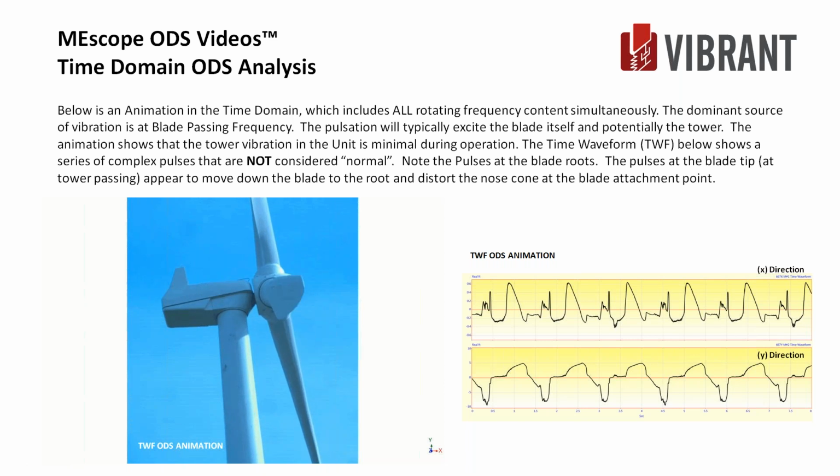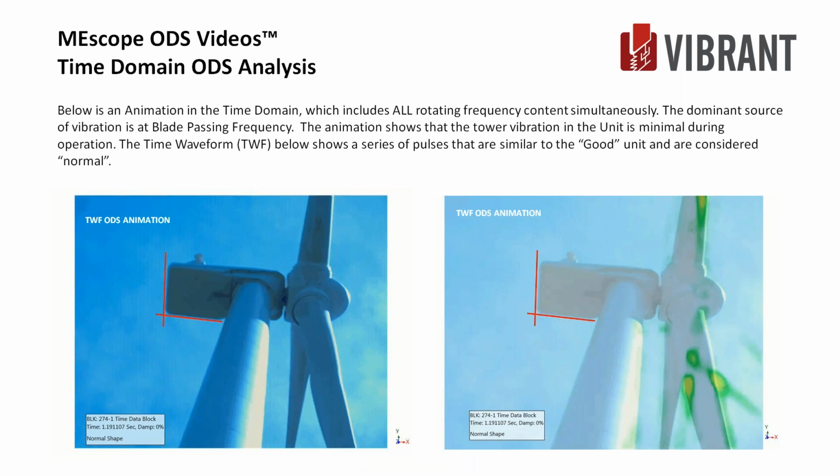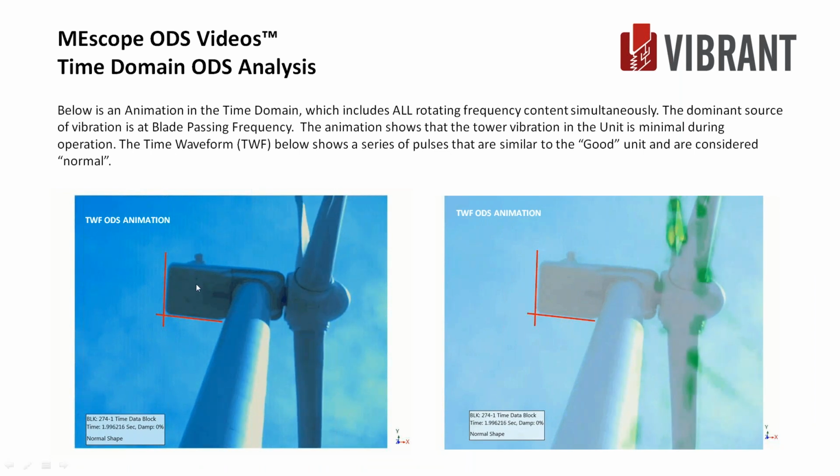And what I've seen on some of these is as I pulse by the tower, the whole blade doesn't tend to move until it's off of that position, then it starts to wobble a little bit like it did there. Okay, so I do see these little pulsations right at the end. I see some blade interaction, and I think I have a color contour one coming up that shows that a little bit better. Yeah, this is the one I was thinking of, but it does show it a little bit better.